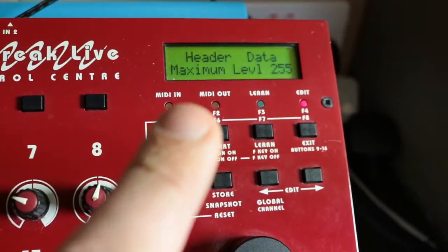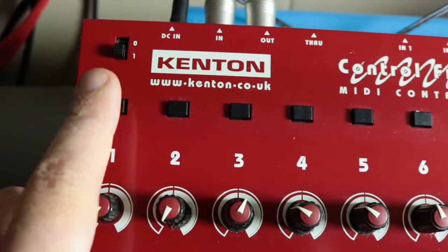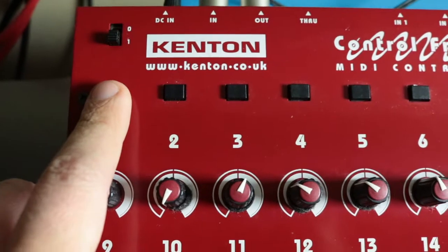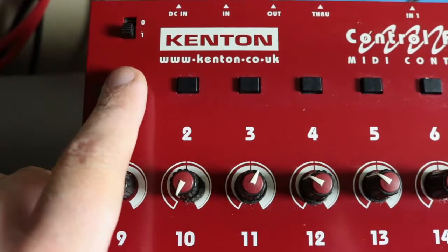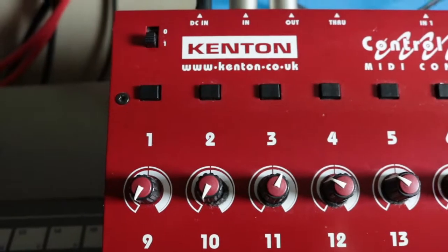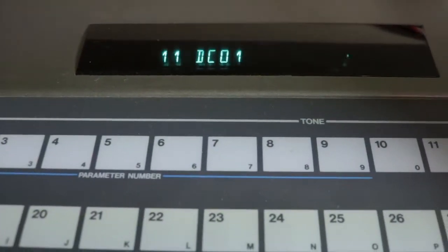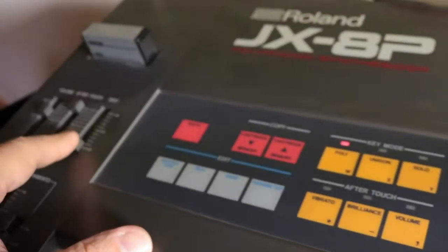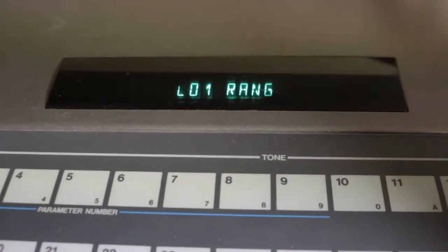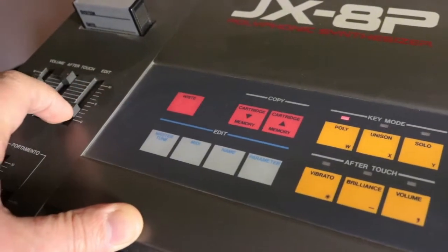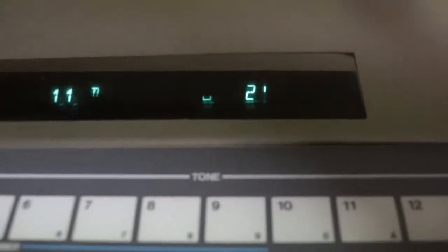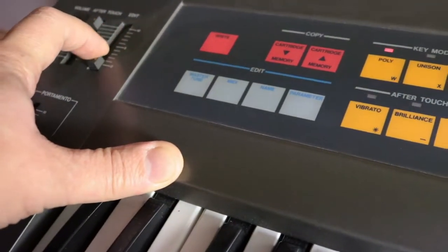What we want to do is set 0, because if we want this to make it go to 16 feet, then we want this button to send 0 in the System X data slot. I can show you that, because if we go to the JX-8P, to parameter 11, which is the DCO1 range, as we slide this up and down, all the way to the bottom, it's 16. As I take it up, it goes 8, 4, 2. When I'm at 2, I'm at the top. So when we're sending 255, we're changing it to 2 feet. And down the bottom, when we're sending a value of 0, it's 16 feet.